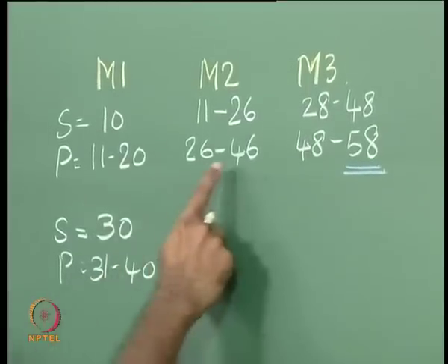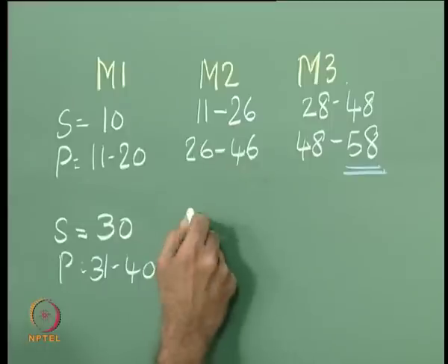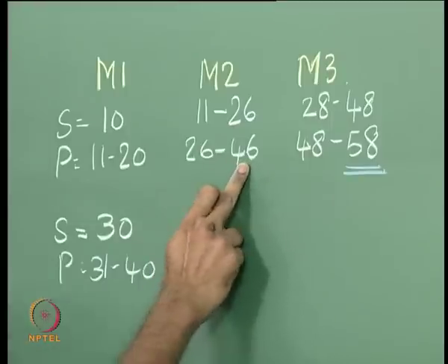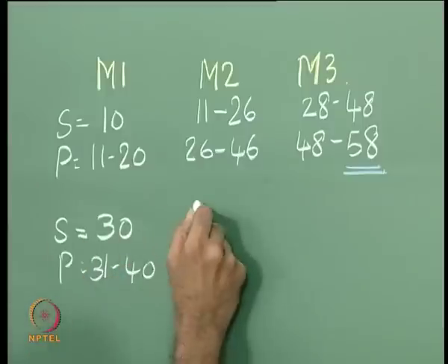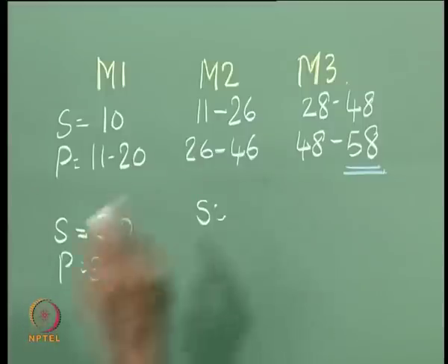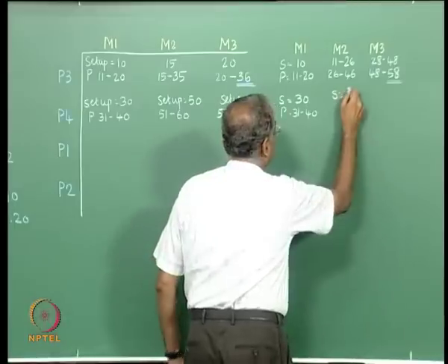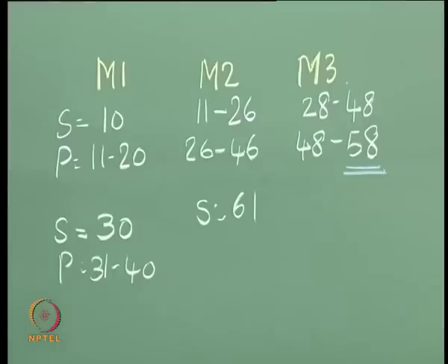Here this is over at 46, so we can actually begin the setup because the first piece would have come by that time. So setup will be over at 46 plus 15, 61. The time taken to produce is 1, so production will be 61 to 71.